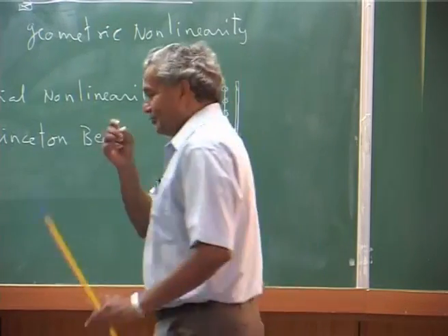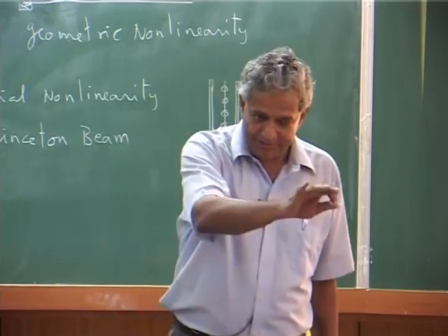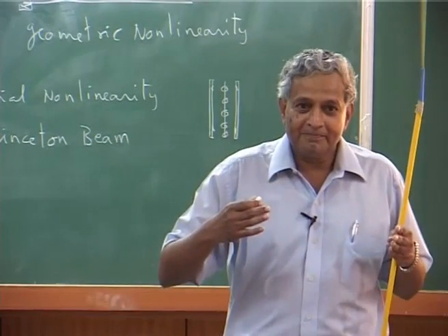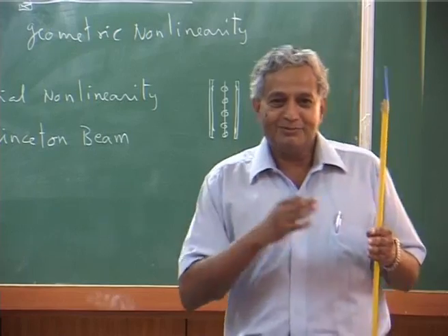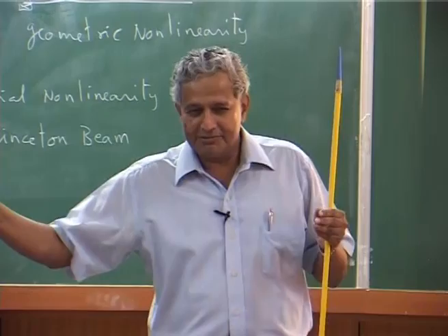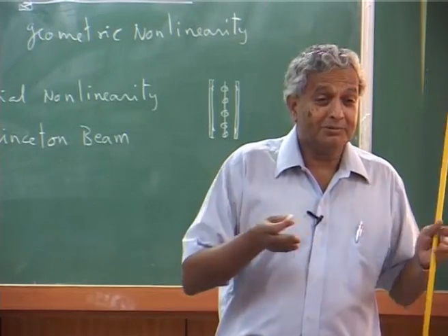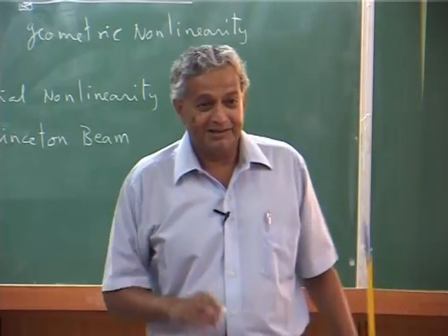See, okay, you are always thinking this is another problem. We always think, if you draw the bending moment shear diagram, please understand, for a cantilever beam, we always say the root has the maximum bending moment.